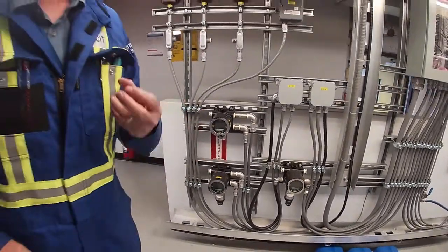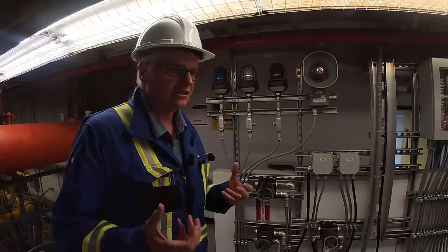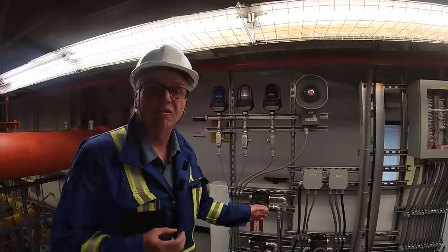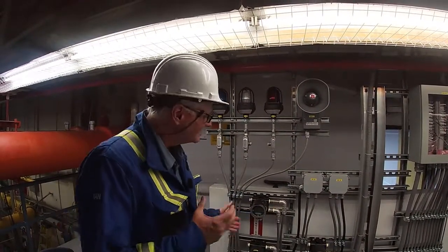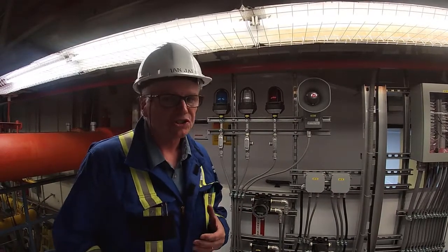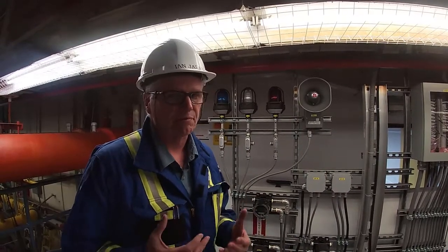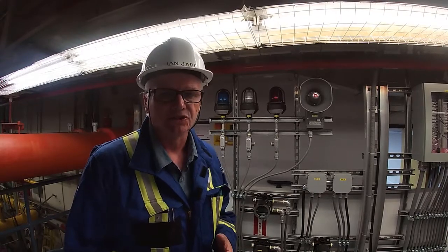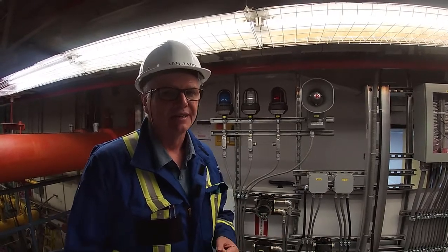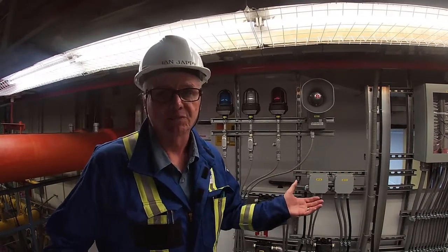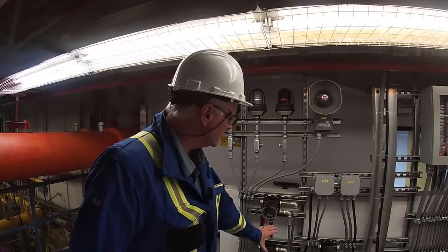The way that they sense the gas in the atmosphere is they're all electrochemical cells. So depending on how much usage you're getting with them, you might have to replace the cells every 1 to 2 years, depending on the plant you're in. Some plants are every 6 months. So those are the detectors.